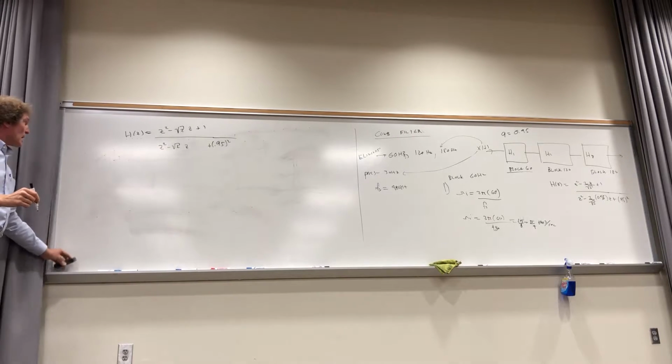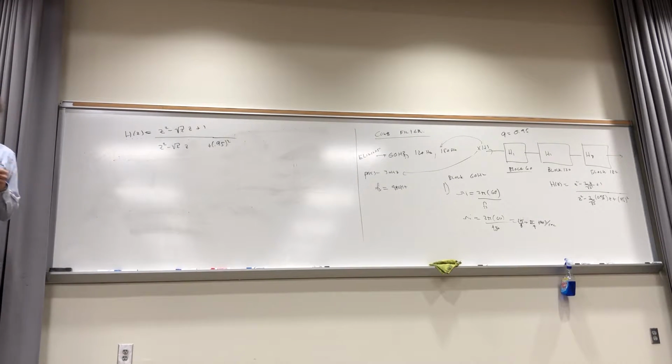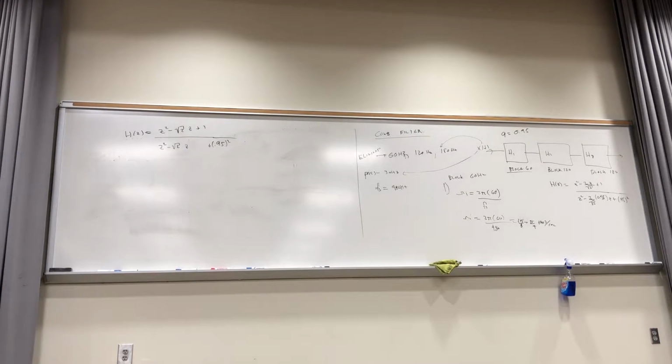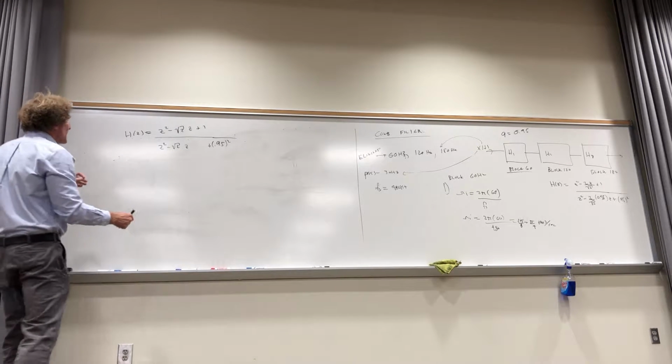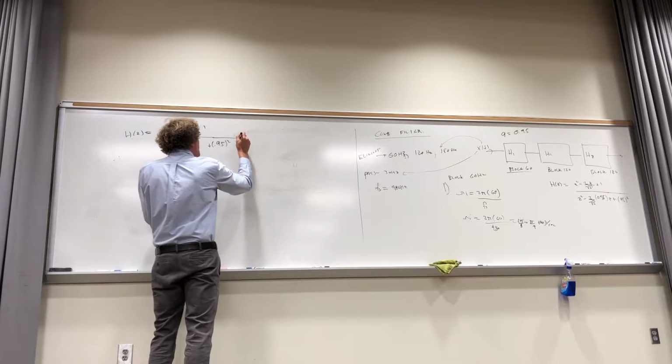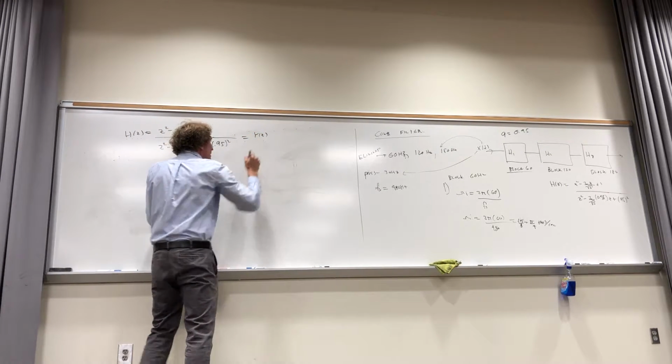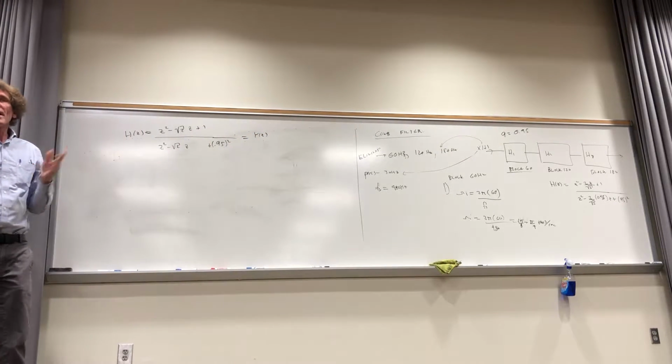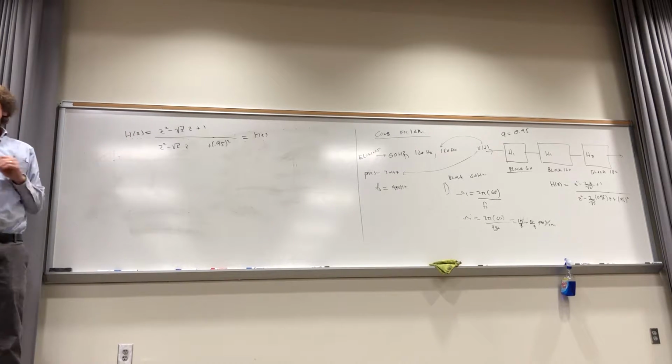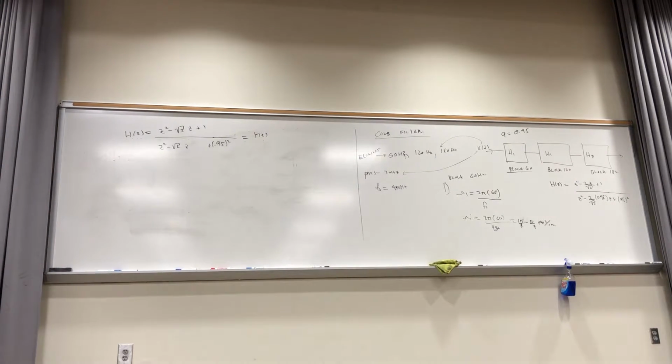Now that I have that, the next thing I need is a difference equation. Do you all agree with this, class? If I want a difference equation for this, I know that this itself is y of z. I could do one other thing. Couldn't I put z equals e to the j omega, and I could get the defined filter response, correct, class? You could then actually plot that.